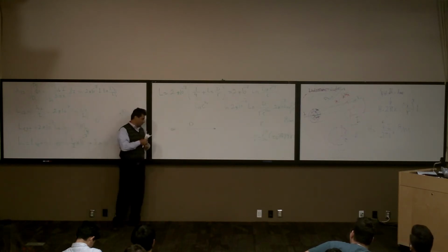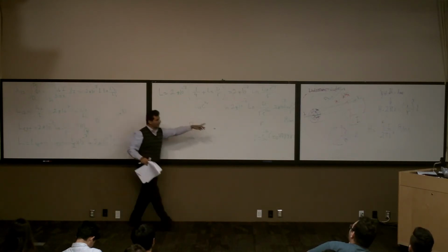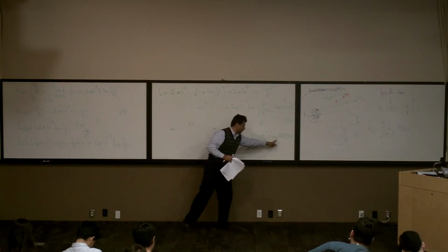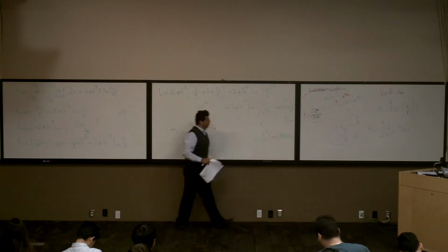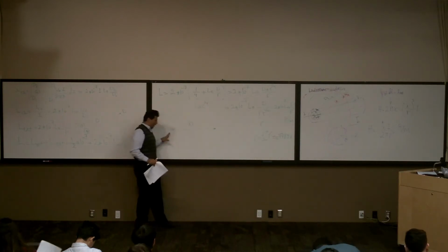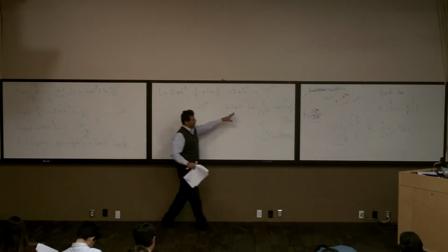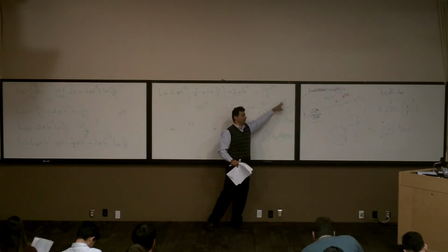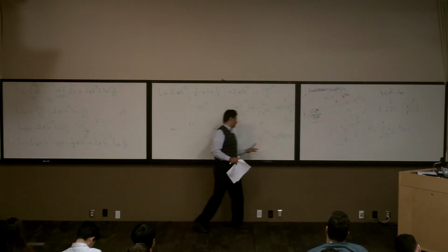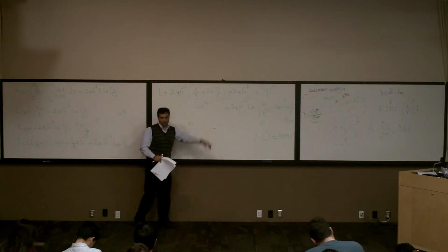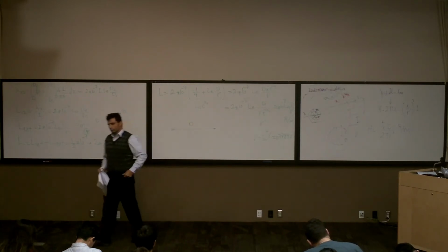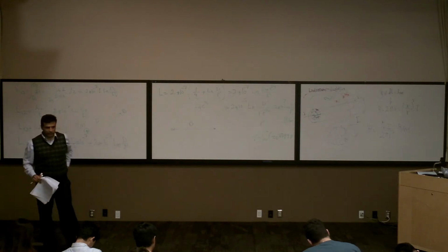The radius of this wire is R. The equivalent radius is going to be 0.7788 times R. So the total inductance of this system is going to be 2 times 10 to the power of minus 7 ln of D over r prime, where D is the distance to the center of this wire. This is what you need to calculate the inductance of the wire.